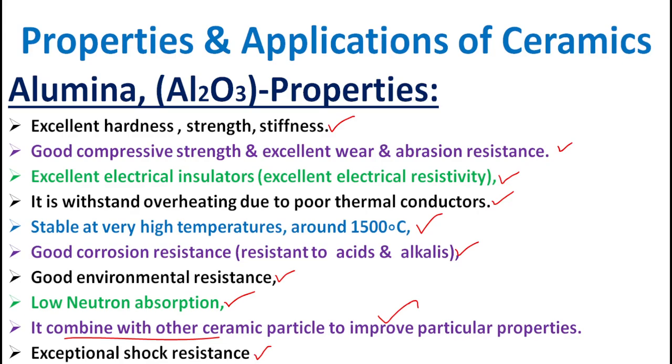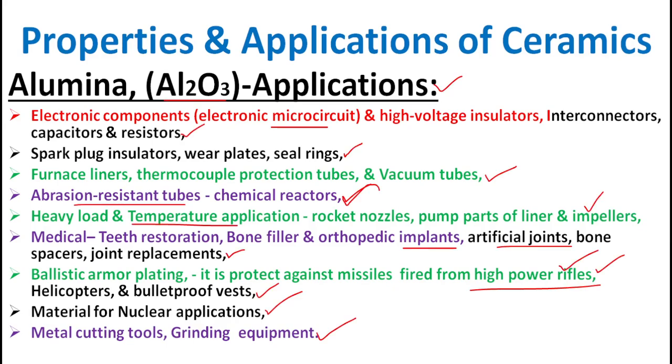So the properties: excellent hardness, strength, stiffness, good compressive strength, excellent wear and abrasion resistance, excellent electrical insulation, withstands overheating, stable at 1500 degrees Celsius, good corrosion and environmental resistance, low neutron absorption, can be combined with other ceramic particles, and excellent shock resistance, mainly used for vibration. Applications: electronic components, microcircuits, high voltage insulators, interconnectors,